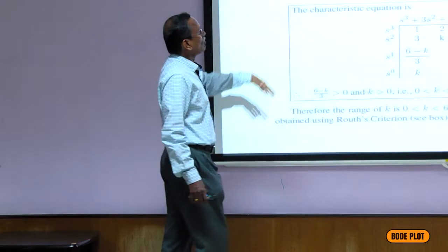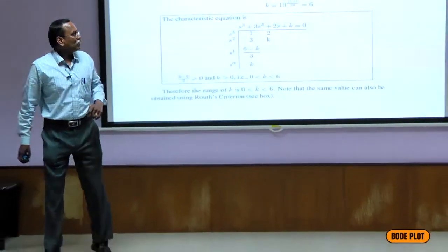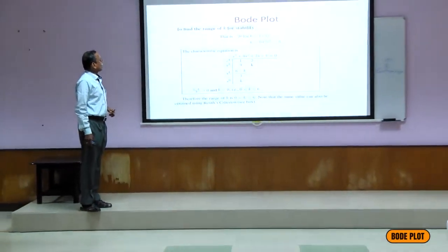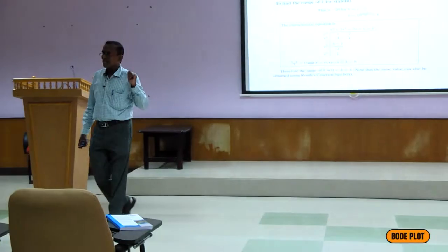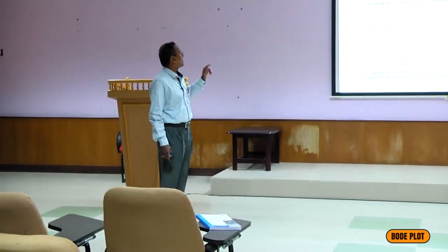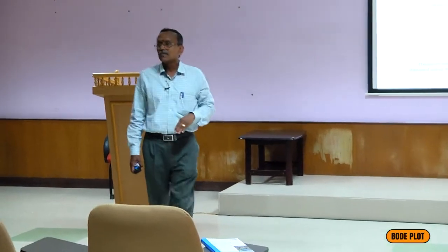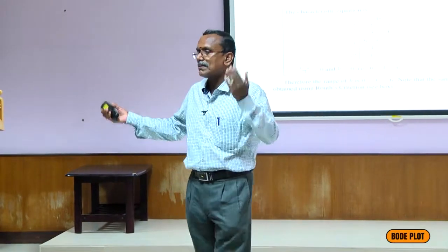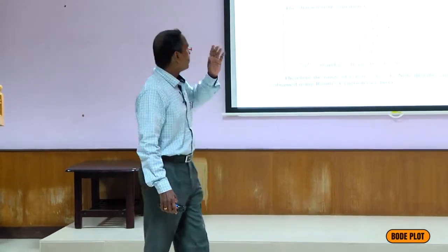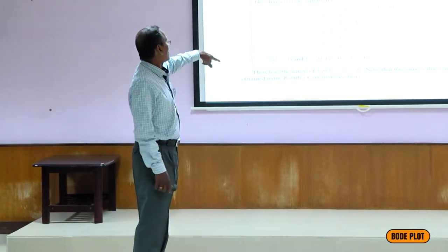The same can be found from Bode. So in Bode, 20 log k equal to the gain margin. What is the gain margin? 15.57. We have seen the gain margin is 15.57. 20 log k equal to 15.57, so k equal to 6. So if you increase the gain by 6, the system enters the range of instability. It will exhibit sustained oscillation. After that it becomes unstable. So from the Bode plot also we can find k max. That's why both are compared.